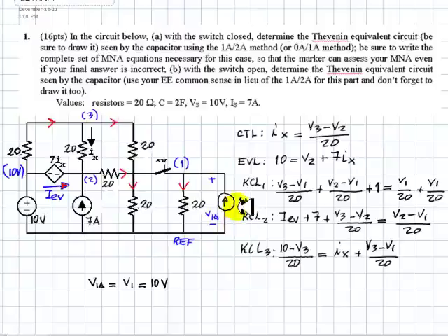We replace this current source with a 2 amp current source, and we find this voltage again, and now we call that V2a, but it's still V1. Good. In the equations that we still have in the memory of the calculator, we only replace this 1 with the 2, press the solve key again to find V2a. Again, that is a new V1.